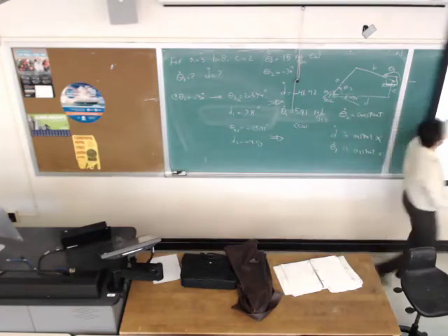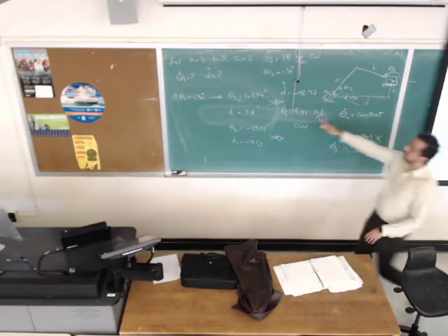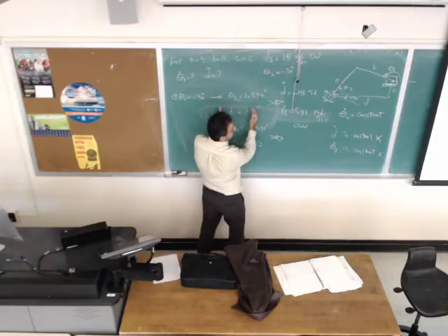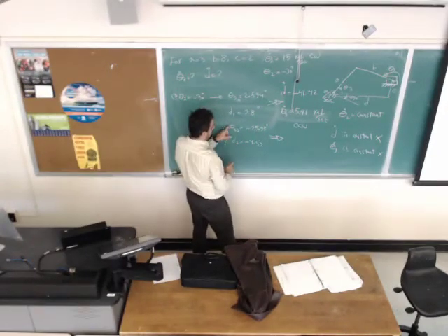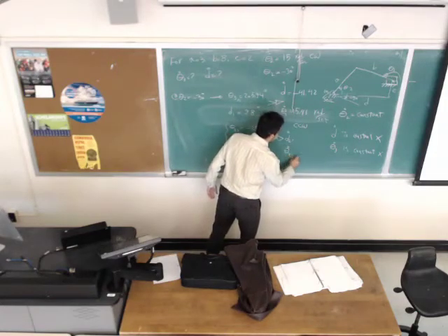Back to the displacement analysis, we had this quadratic equation, we solved for D, and then back to those equations that we derived to find theta 3. So the M and the N are just the same ones from the last time we did the displacement analysis? Yes, I just copied and pasted. Okay. This is from theta 3.1? Theta 3.1, yes, this is for mode 1. You can just repeat with the updated values to get d dot for the second mode and theta dot 3 for the second mode.